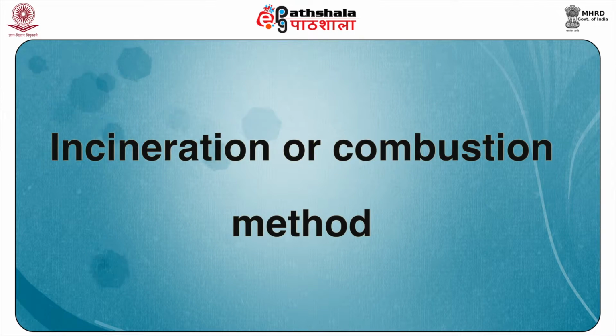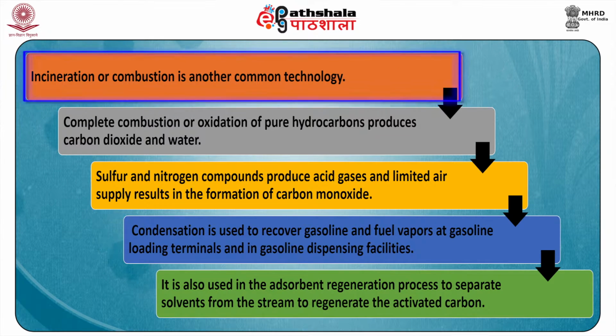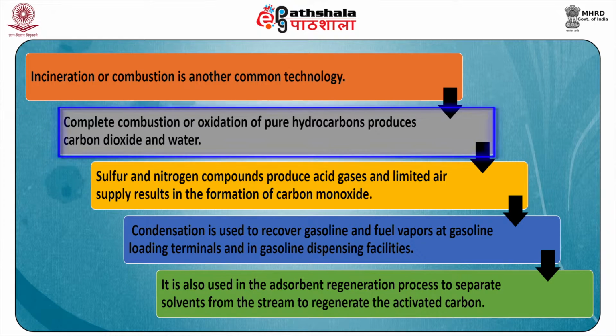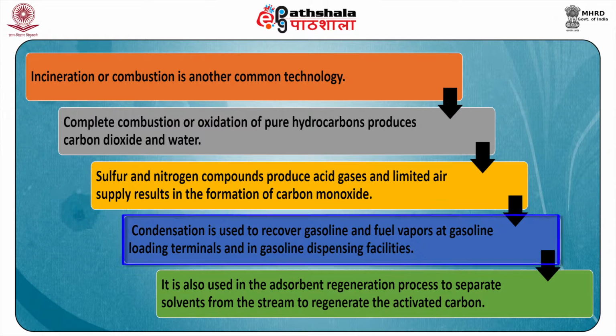Incineration or combustion method. Incineration or combustion is another common technology. Complete combustion or oxidation of pure hydrocarbons produces carbon dioxide and water. Sulfur and nitrogen compounds produce acid gases, and limited air supply results in the formation of carbon monoxide.